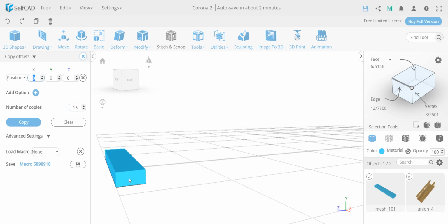Now, if I need to make 15 steps, I need to move this. In this case, I do not need to consider half of the object because it's delta based, the amount that I'm moving by. So I need to move it in the Z direction by 50. That's what I know for sure, because the size is 50, I need to move it by 50. Then I need to move it in the Y direction. This is where it becomes interesting. I need to move it by 12.5, not by 25. 25 will make it high, and I'll show you in a minute why. 12.5, okay? And actually, because I'm moving it in this direction, this is actually negative 50. Otherwise, it will give me the opposite results. This is negative 50. I'm moving it in the negative direction, 50, 12.5.